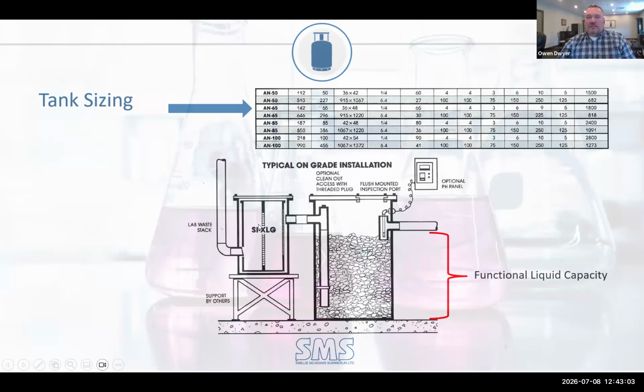That dip tube is necessary because without it, you have laminar flow. It's just going to come in and go out. You're not interacting that effluent through that stone bed. So again, attention to detail, specify the interceptor. I'll talk about interceptors later and their importance. They're basically protecting that dip tube. And then the support, the stand for the interceptor, for example. I've seen cinder blocks, I've seen milk crates, and I've seen contractors suspend what would be a 100-gallon capacity tank using threaded rod because they hang it while it's empty, not knowing that the thing is going to weigh 500 pounds, from Hilti pins in the ceiling.